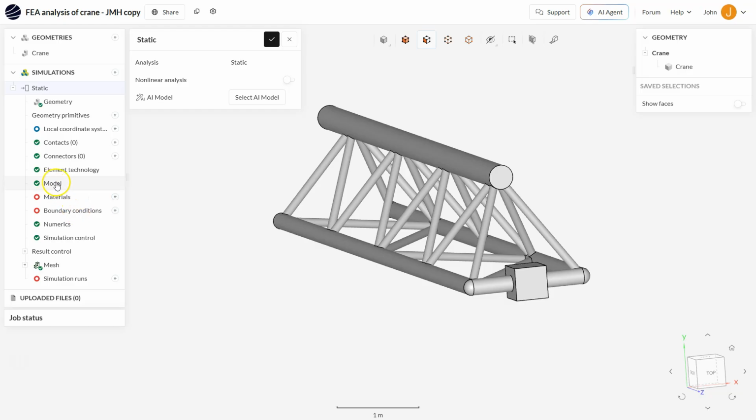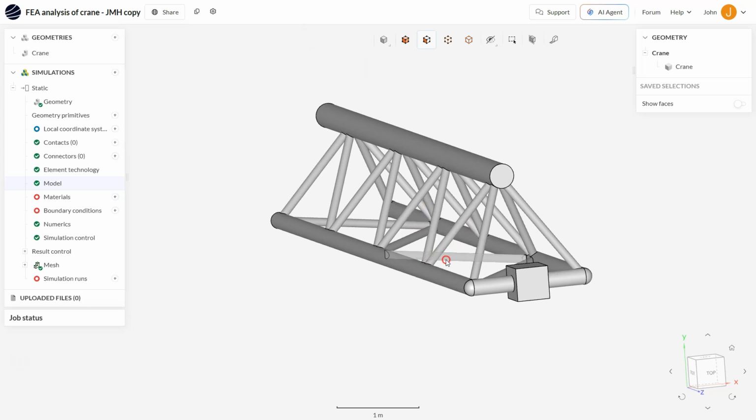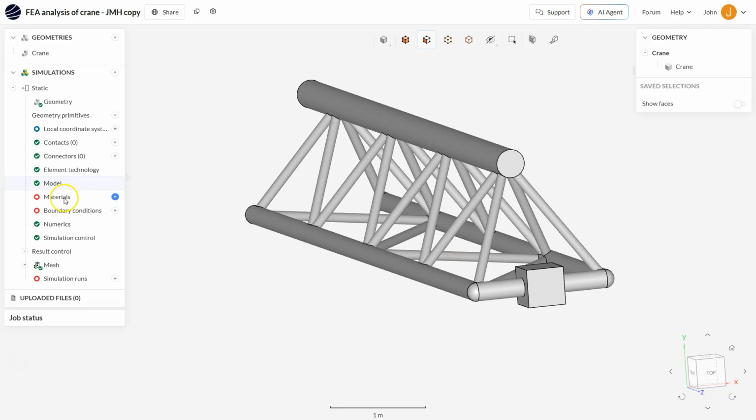The first thing we need to define is the model, which is basically gravity. So the magnitude of gravity is 9.81 because we're doing this on planet Earth, and the direction is in the Y direction. If you look at the bottom right, we can see Y is vertical as expected, X and Z are as defined. So we want this in the Y direction, but it's -1, so that's going to be acting down. And this little blue arrow shows us the direction of gravity, which is great. What else do we need?